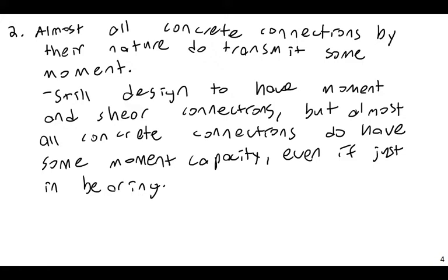Today we're going to be looking just at the concrete columns that don't have moment, so short concrete columns without moment applied. But I want you to keep in mind that this is kind of an edge case. In most cases, you are going to have some level of moment, and we need to use what's known as a moment axial force interaction diagram, and we will learn about that next time, or perhaps in the next video.